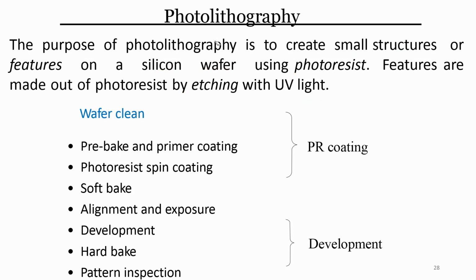Now, when you talk about photolithography, there are several steps involved, and the first among them is wafer cleaning. You should not start any process in microengineering without cleaning the wafer. Cleaning the wafer does not just mean cleaning with DI water, or drying with nitrogen, or just pre-baking it. Cleaning of the wafer means, like we have discussed in earlier classes,